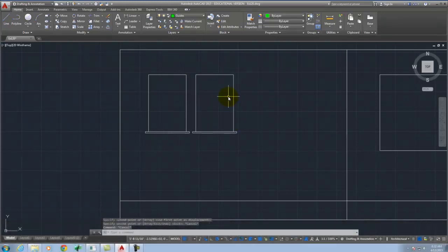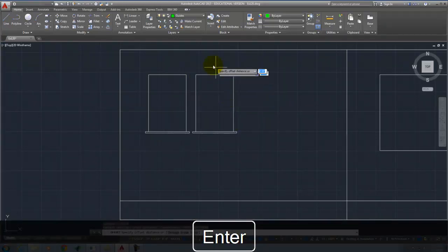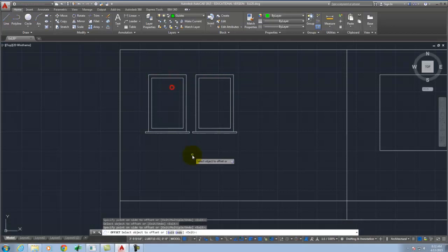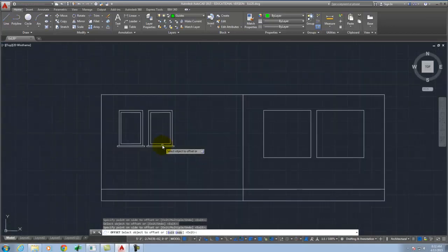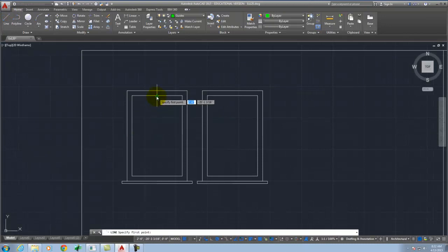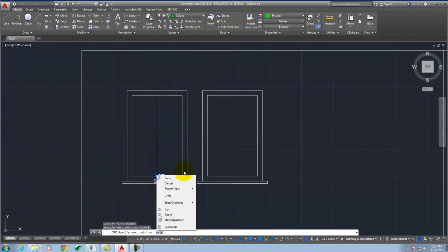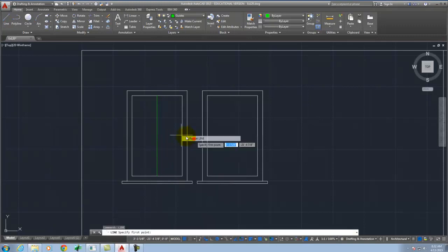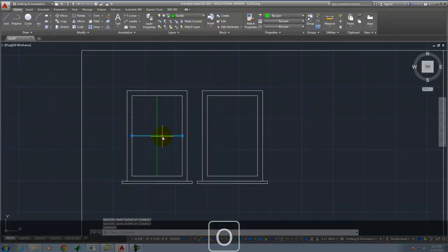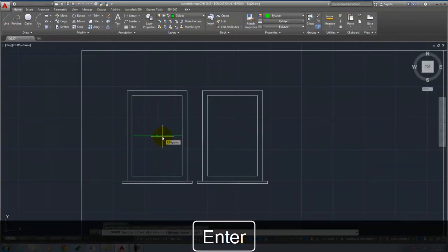Let's put a frame inside the window. So we'll go offset. I don't know. Let's do 2 inches. Give ourselves a little bit more detail. See how we're trying to add a little bit of what a window would look like? If you're struggling with what you want your window to look like, Google search windows and take an example. Maybe we want to divide it up so we have a little frame in here. Remember these are the same size windows, so I can draw it once and copy it. Let's do a little offset. Let's do a 1/2 inch.